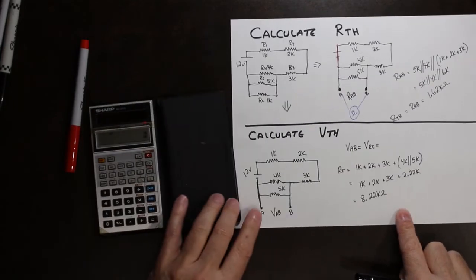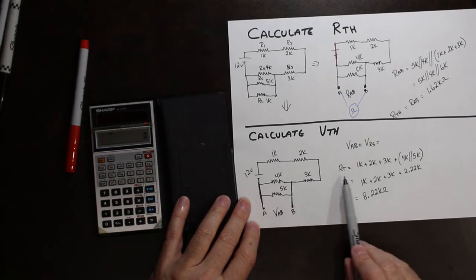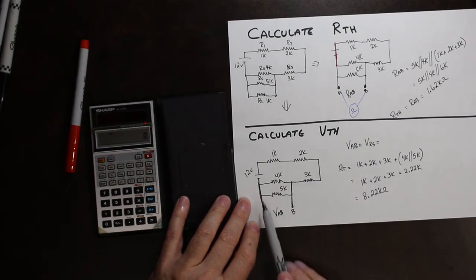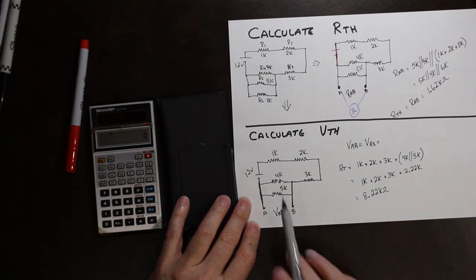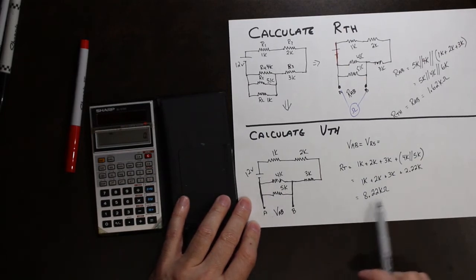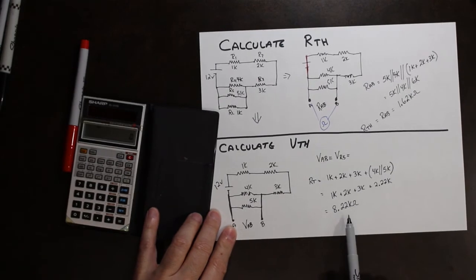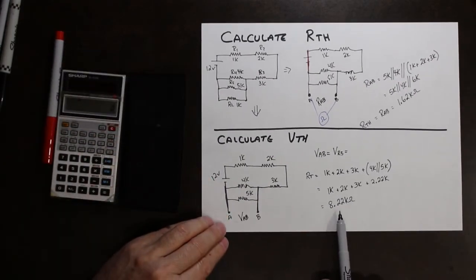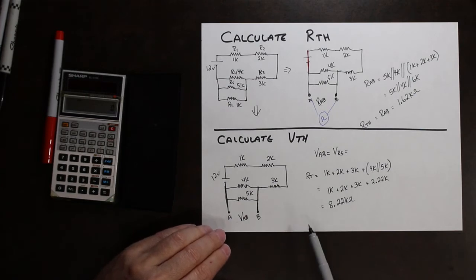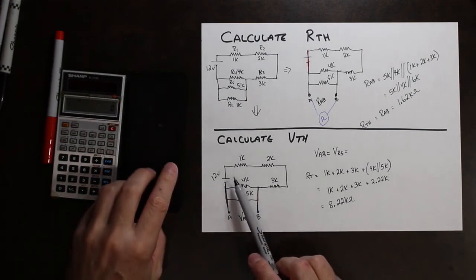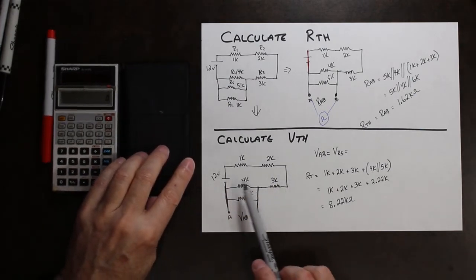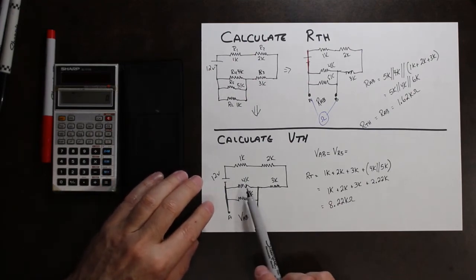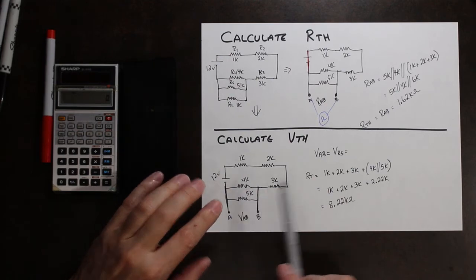So we want to find the voltage across from point A to B, which is across R5 or R4. There's a few ways we can do that. Now that we have this value here, we can actually use our voltage divider and figure it out. Or if we wanted to, we could use Ohm's Law, so calculate the current and then figure out how much current is flowing through each of these resistors, and do it all.